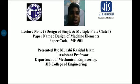Otherwise, if you do not select the proper material, you cannot do the proper design of the clutches. The frictional material should be able to retain its frictional properties during the service life. And point number three, there should be a provision for adjustment of worn out friction plates or surfaces.